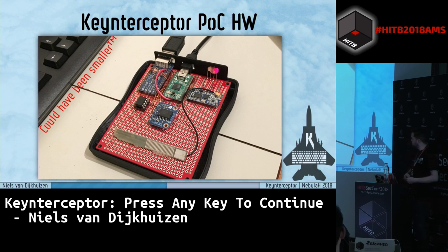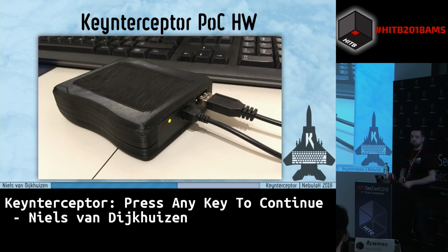This is what I came up with. It's a bit big, it's a bit bulky, but well, it's a proof of concept, right? And I could ditch the EEPROM because the Teensy controller has an option for it. But you get the idea. The USB host, the microcontroller, the brains, the communications module with an antenna, the battery-backed clock, and the configuration, built into a printed case.